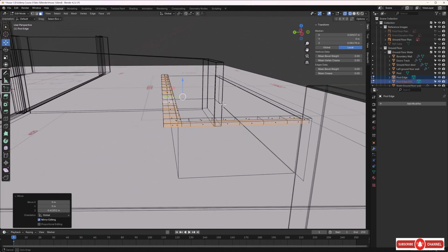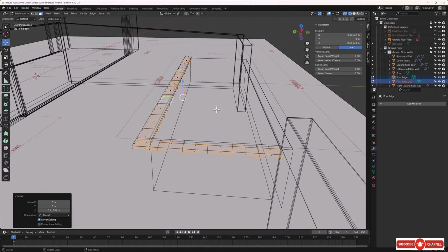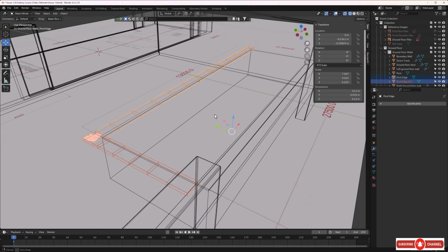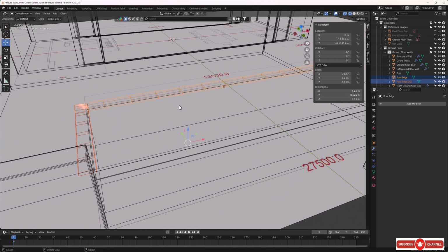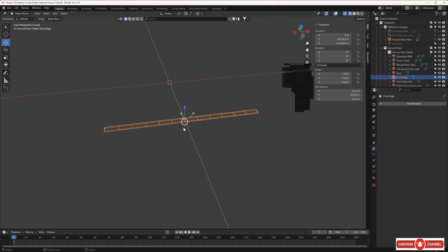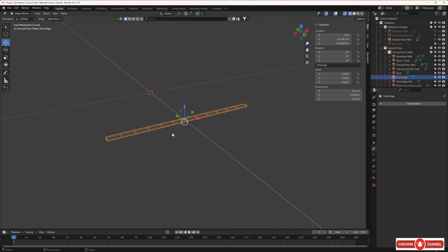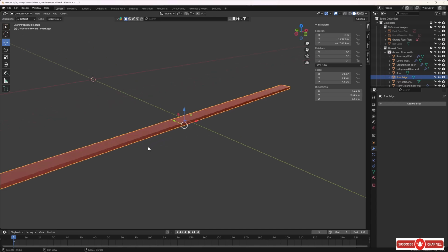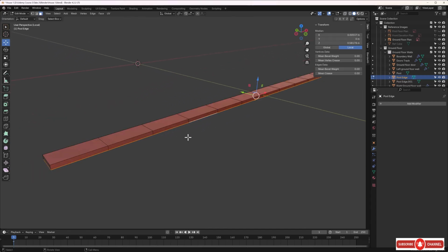That's cool. So now we have them at the right height and the right thickness. Okay, so now we need to start applying some bevels to these. Let's tap out of edit mode for just a minute actually. And let's just select maybe just this longest one here. And let's hit the / key on the numpad to isolate it. And maybe now we work in solid for a while, so I'll press Z and go over to solid. Let's hit the tab key to tap into edit mode.